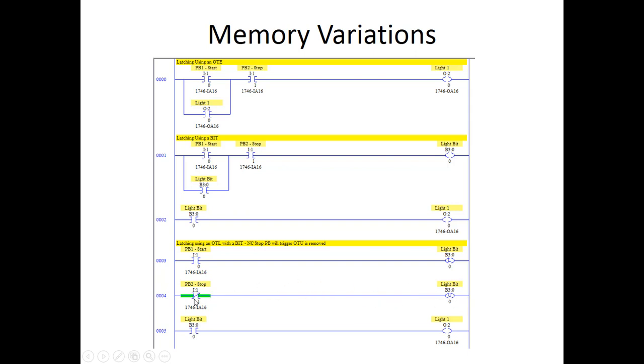Okay? Now be aware here that if the stop is wired normally closed, that pushes a 1 into the data table. There'll be an indicator light on the input module. So this will get a 1, and so this will be reading false. This will be reading open as false. So when I push the stop button, this will return to the state indicated, and then the bit will unlatch. And then here's the contact. We're using the bit to turn the light off and on.